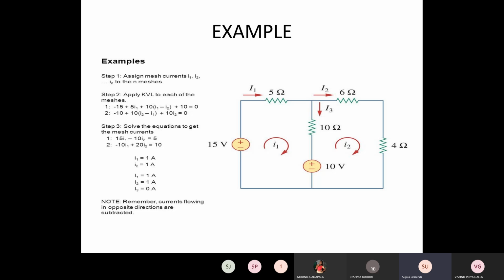So we take this circuit, and simply you have to do the problem, and then after writing the two equations of the algebraic sum of the voltages, you can use Cramer's method or the direct equations method to solve for the total currents flowing in the circuit. So in this, simply you have to observe how many loops are there. Second thing, entering current will be plus, leaving current will be minus. And third thing, to write the KVL equation, the algebraic sum of the voltages is equal to 0.